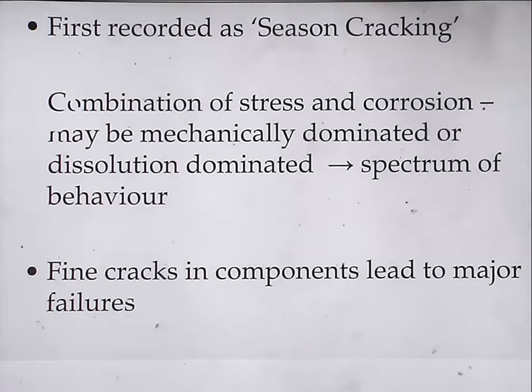As soon as you got a humid environment, the manure that the horses were generating has an ammonia content to it, and the ammonia combined with the moisture gives you ammonia cracking of the brass. Extremely serious situation, because you're then out in the middle of somewhere on a campaign and you actually don't have any ammunition. So highly embarrassing. You have to keep it very secret, otherwise you get wiped out.